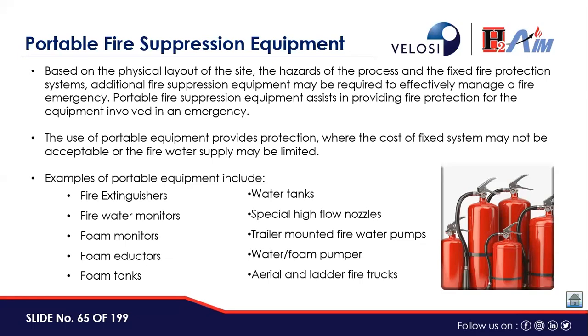In this way, the QRA modeling and dispersion models provide the location where the fluid may affect, and if those areas are required to be protected from fuel leakage or rupture effects or fire effects, then accordingly fire walls are installed and the ratings are defined based on UL requirements, whether 1 hour fire rating or 2 hour fire rating, and to prevent the pressure as well.